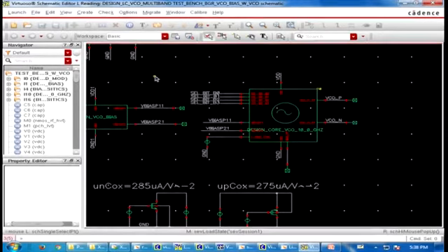Okay. Test setup, have I shown you, right? Yeah. Oscillator, buffer, pad. The pad is protected by ESD and you have a circuit. The buffer, do we have any specification? I say 1 milliwatt power. No, the buffer which is the output of the oscillator is connecting, right? So the buffer is inside the chip. Inside the chip. So the buffer has to be considered in layout as well as schematic itself.